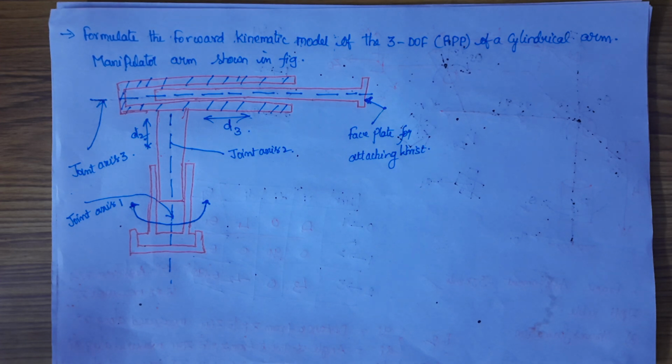The cylindrical configuration of a manipulator has 3 joints. The first joint will be the revolute joint, while the next two are prismatic. The axis of the first two joints coincides because this configuration has a cylindrical workspace, as discussed in the question.